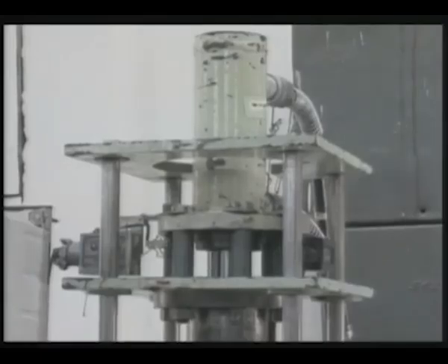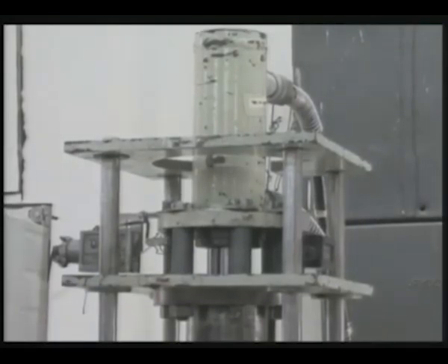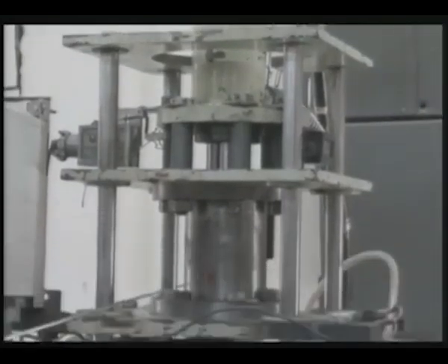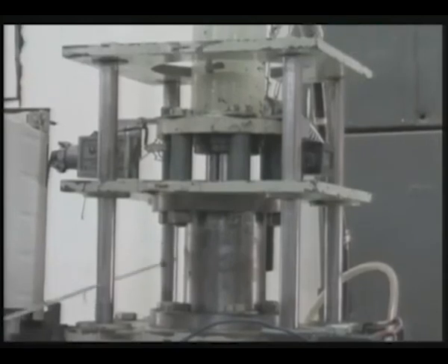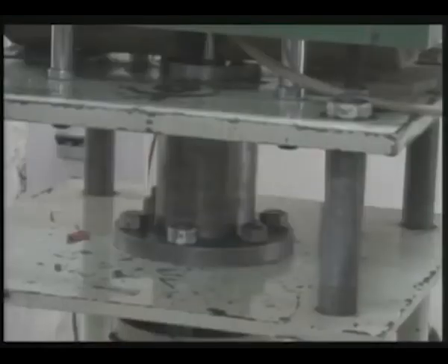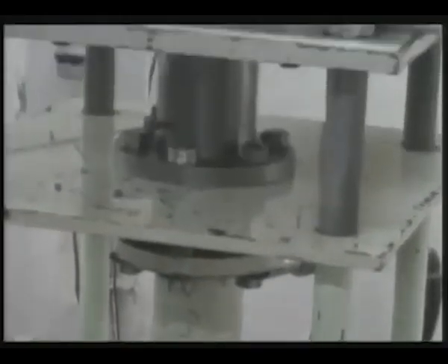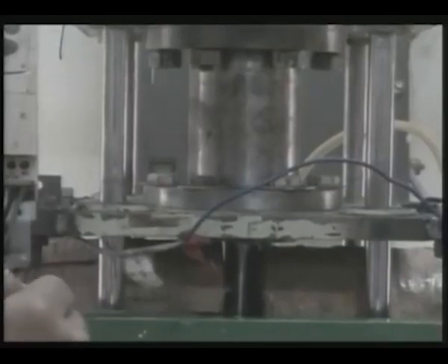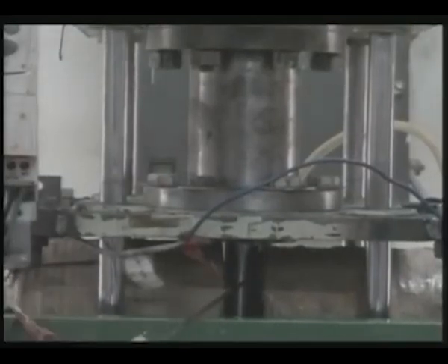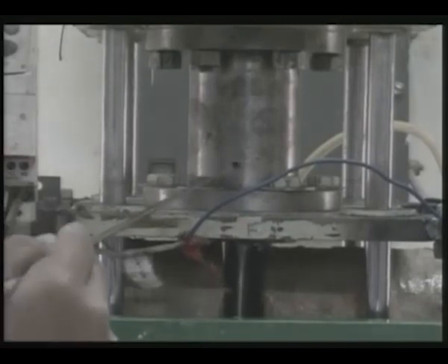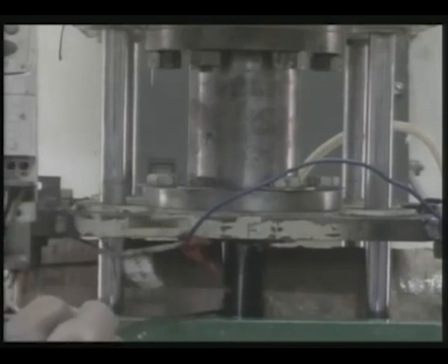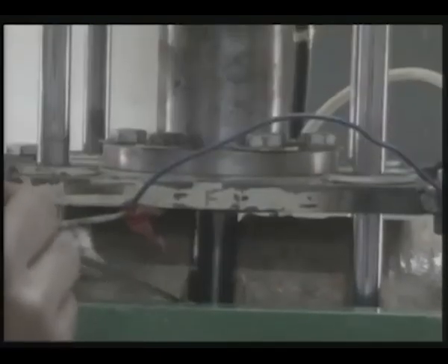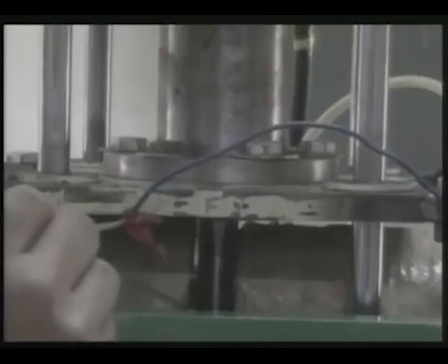Another part of the magnetorheological abrasive flow finishing process is the hydraulic cylinder and this is the media cylinder. Two cylinders are on the top side, and two cylinders are on the bottom side also. This is the workpiece fixture of the MRAFF process. It has three parts. The top guiding attachment is there to flow the polishing media from the top media cylinder to the workpiece fixture, the finishing zone of the process.